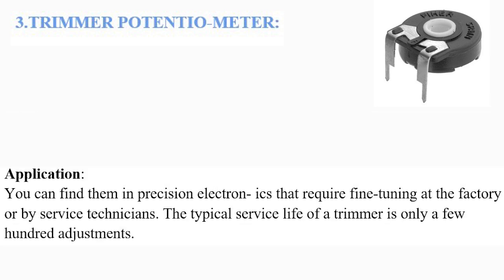Commonly, trimmer potentiometers are used in audio equipment, calibration circuits, and adjustable power supplies. You can find them in precision electronic ICs that require fine tuning by service technicians. The typical service life of a trimmer is only a few hundred adjustments.